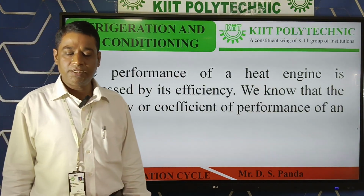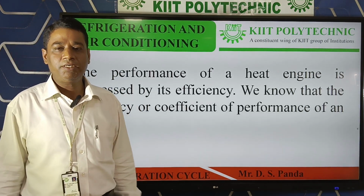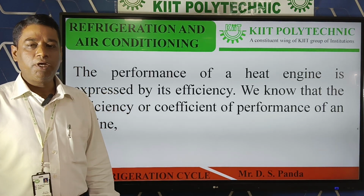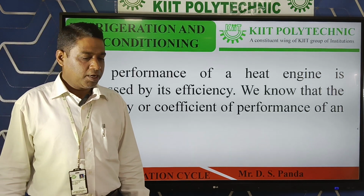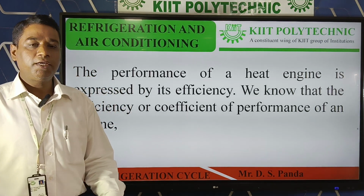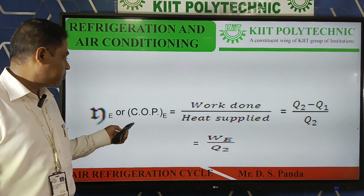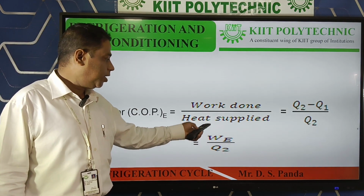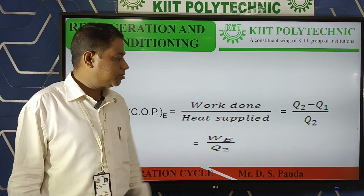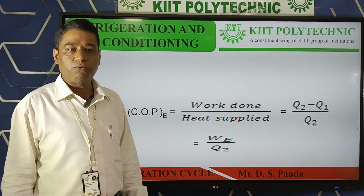The performance of a heat engine is expressed as the efficiency of the engine. Normally, efficiency is always the ratio of the output to the input given to the system or machine. And here in the engine, the output is work done and the input is heat supply. So efficiency of the engine equals work done divided by heat supply, and work done equals Q2 minus Q1, divided by heat supply Q2. That is, work done by the engine W divided by Q2.